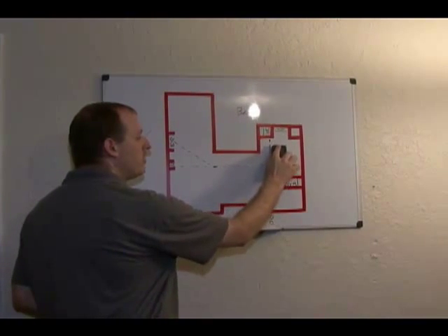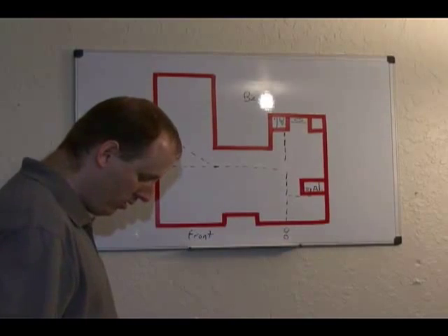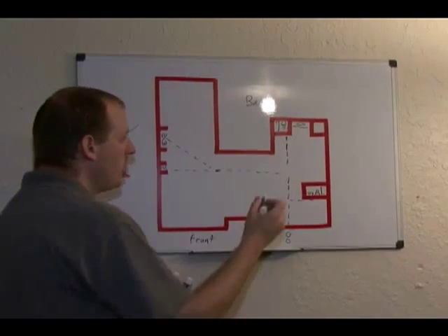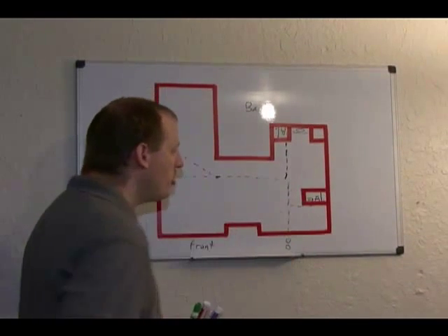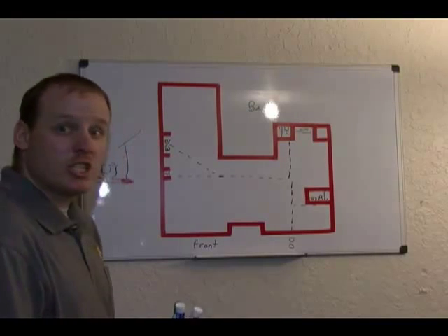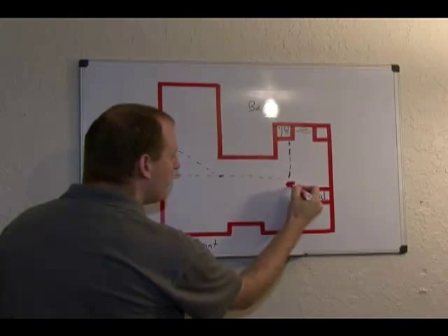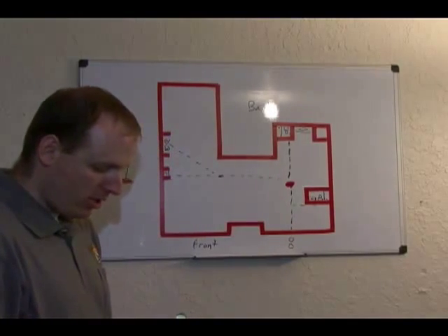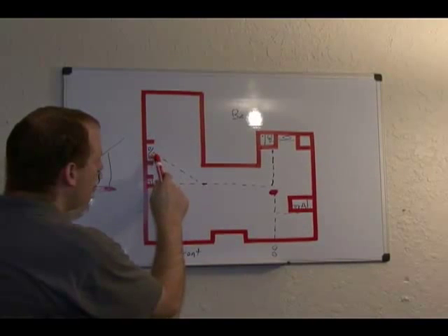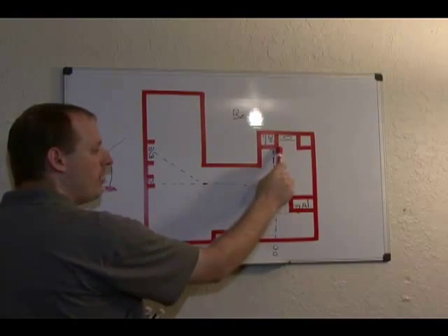At that point, we would remove that test ball and start another test, which in this case, what we would do is then move the test ball just a little bit and place the test ball right here. Okay? You see now what we are able to do by doing that is test all of these lines. We already know there's no leak back here.